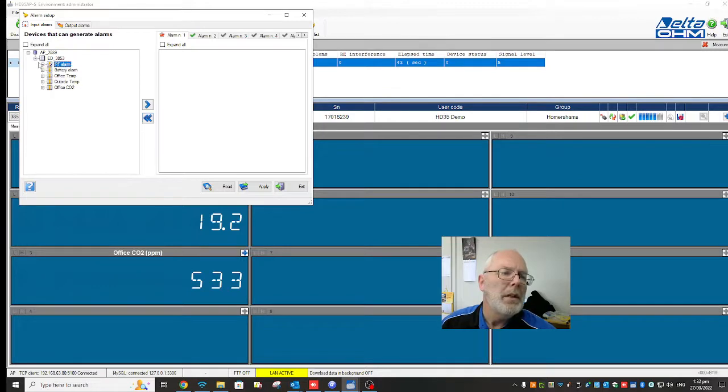So what we do want is to have office temp. Yes, we want to be alarmed at that. So we'll put that across there. Outside temp, yes, I want to be alarmed at that. And office CO2, yes, I want to be alarmed at that. So then if I look at these things here, there we have all the things that will alarm and what they're going to do. Now, of course, we have to hit apply. And as we know, that can take a while.